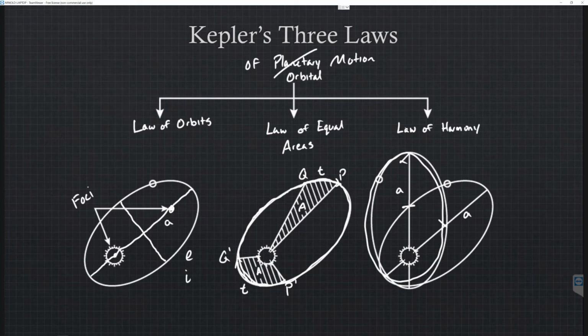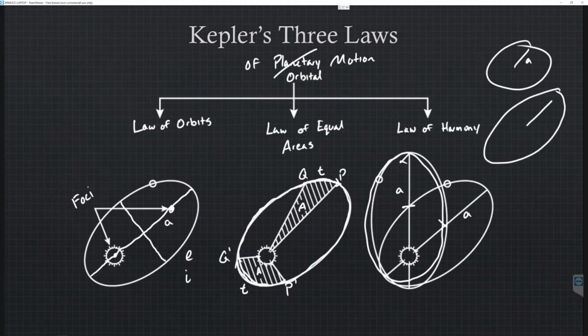This is really powerful because it allows us to take that same equation that we have for a circular orbit, and a circular orbit like here with a semi-major axis of A, and we know the amount of kinetic energy in this orbit. There's actually the same amount of kinetic energy in this orbit as long as A is the same. We might be traveling through certain sections of it a lot faster than others, but the orbital period and the amount of kinetic energy to get into that orbit is exactly the same. So we can apply a lot of simplifying assumptions when doing our orbital mechanics.